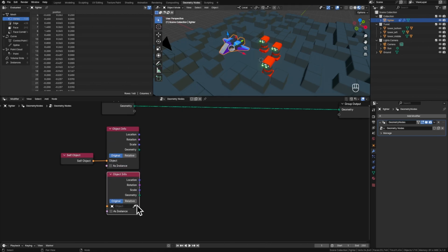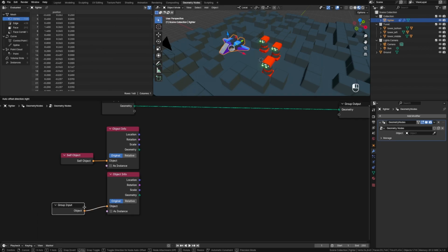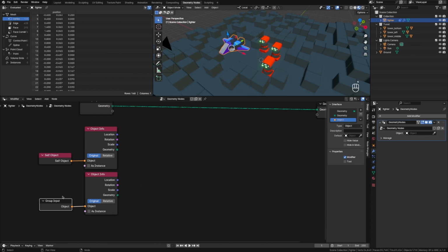And we want to make this so that it's reusable. So we will specify an input as this group input here. And you can see here in the modifier stack, we have this blank object now, and we can tweak the parameters by double clicking here. If you don't have this panel, press N to pull that up and make sure you're in the Group tab here. And then you can type Target, and that changes in the group input here and in the geometry node modifier here. So now you can specify which object you want to target.